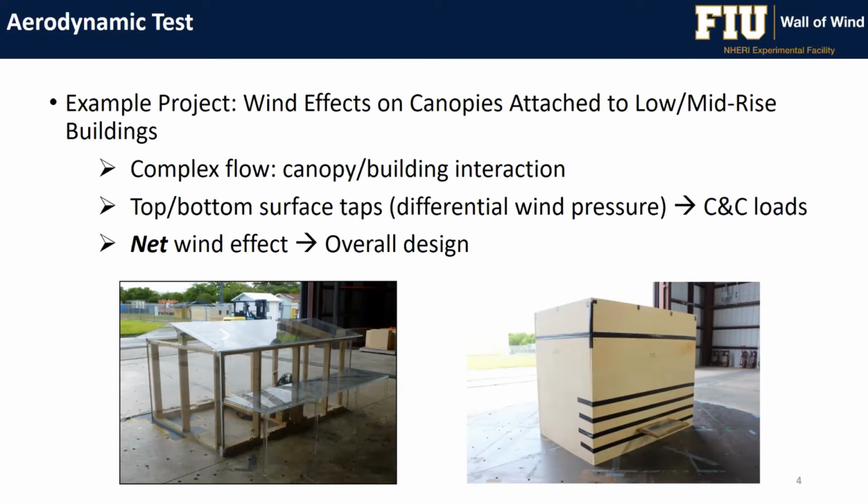in Canada. And you can see here one of the major advantages of using a larger scale. This model was 1:5 or 1:6, if I remember correctly. I think I have this information on the next slide. But one of the advantages is that we can have the patio cover or the canopy designed according to the full-scale dimensions. The thickness of that element is important when we do this kind of study. When we go to scales of 1 to 100 or smaller than that, then we violate that thickness, and using this larger scale allowed us to build a more realistic model.